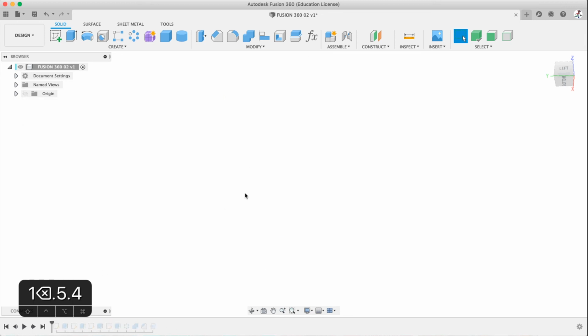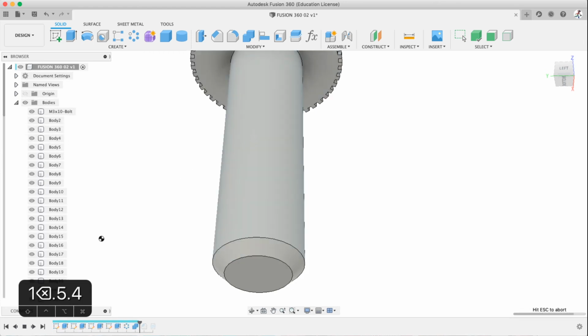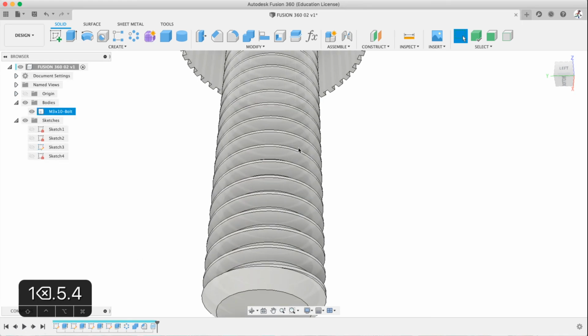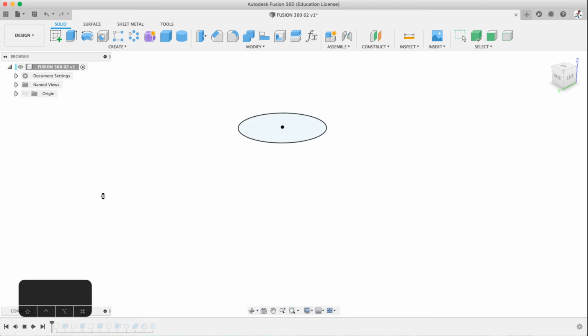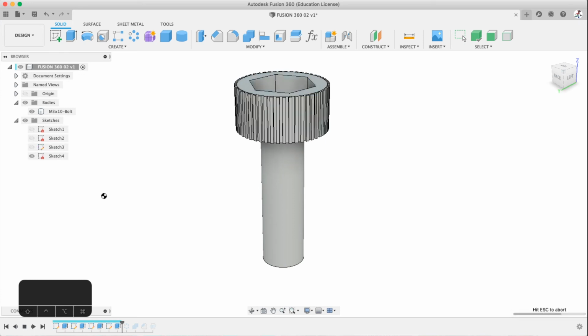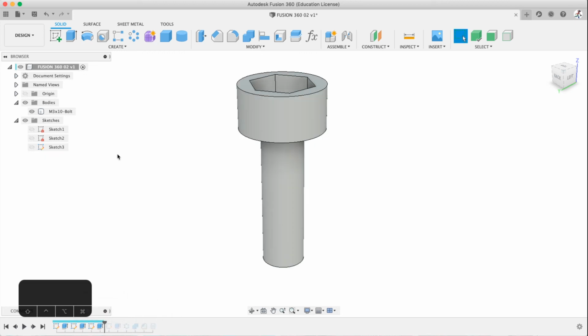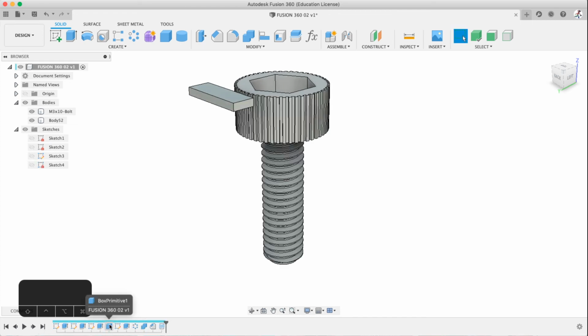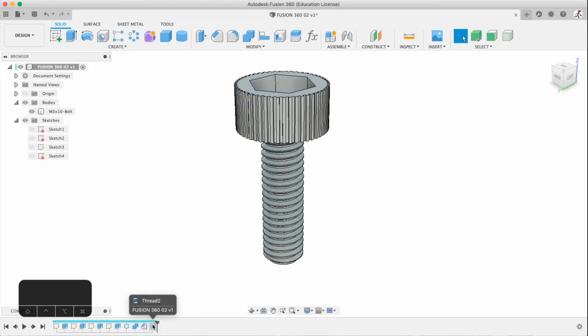I can go back to the very beginning and we can actually watch exactly what we did. You can go slower. Let's go forward. Let's zoom out and let's just see it there. So watch this. Go back to the beginning, hit play, and it shows you every step you did. It's the same idea as going back in time and adding something. Let's say I want to add a box. Now, a box was just added in that spot I went back to. Let's delete it. It removes the box from that spot. Everything after is recalculated.